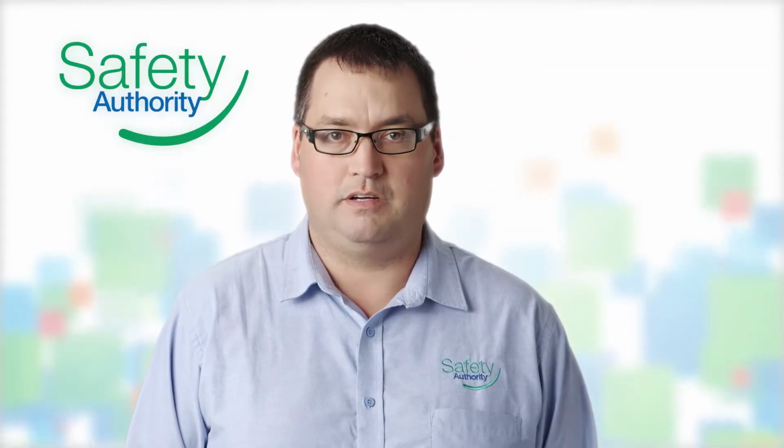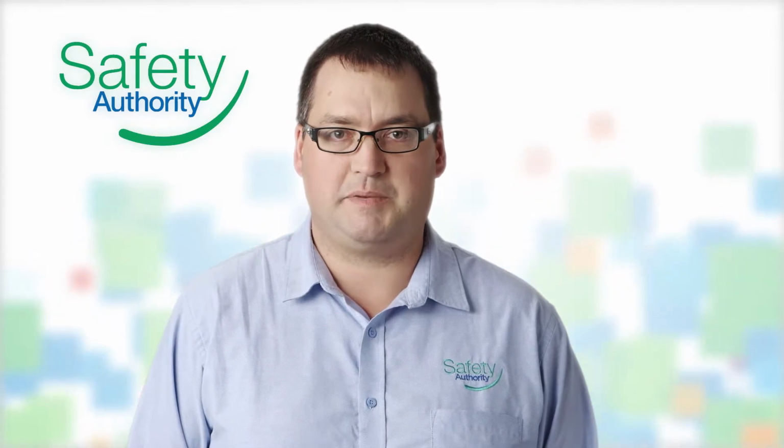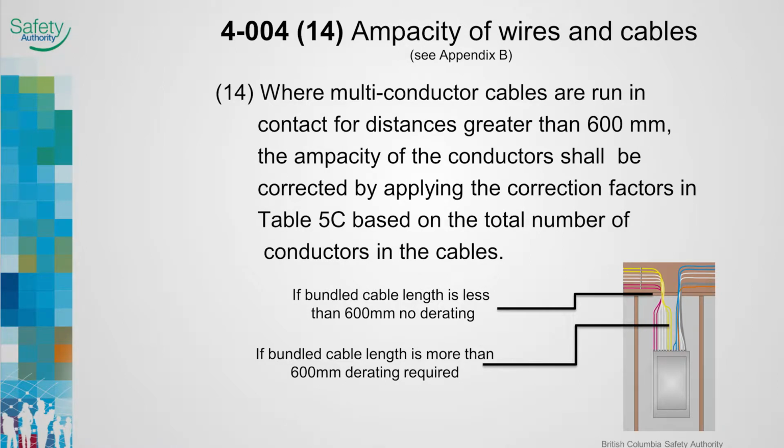Rule 4-004, Subrule 14 is not new, however it has been reinserted since being missed in the last code. Multi-conductor cables run in contact with each other for distances exceeding 600 millimeters require derating by using Table 5C. The derating factor is based on the total number of current carrying conductors in all cables.